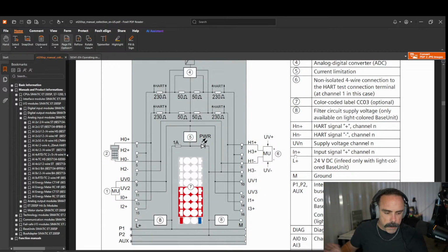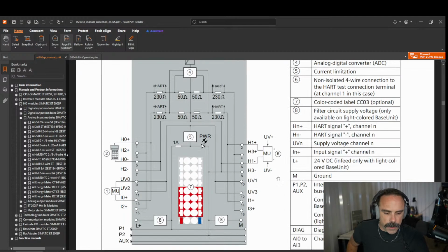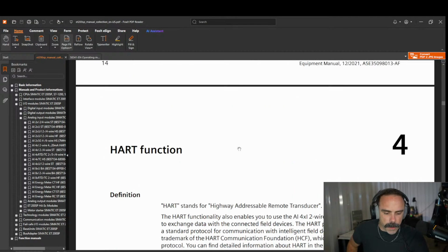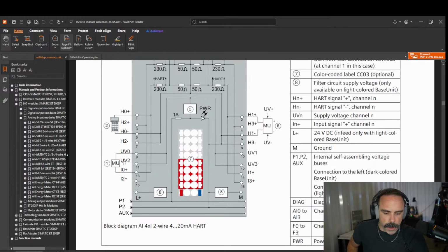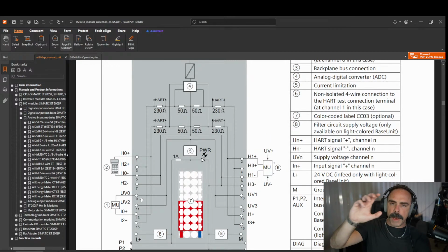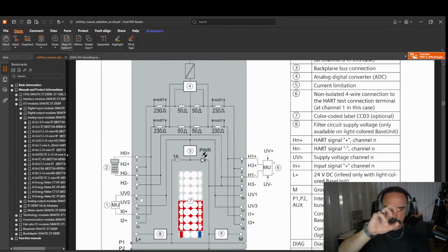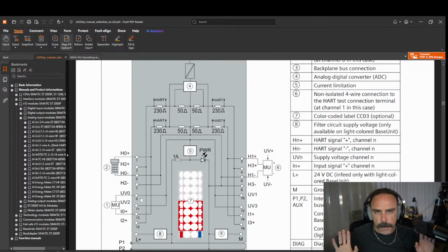So your 2 wire transducers will actually get connected up differently. So you're going to be between 9 and 13, 11 and 15, 10 and 14, 12 and 16 for the actual 2-wire transducer, the 2-wire connection. They get shifted down to the bottom terminal. So just be aware of that.